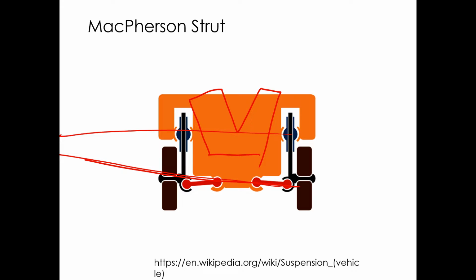So yeah, you get the same tunability on instant centers. The only downside of this is you have to have a nice prismatic joint. You combine that with a shock absorber, which is going to be a prismatic joint anyway, and it's not that big of a deal. The only main issue is this component wears out over time.